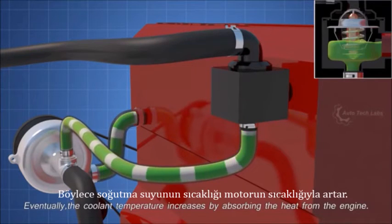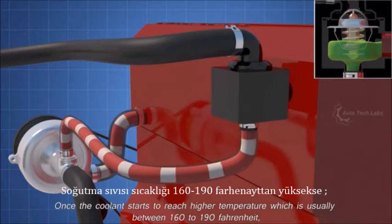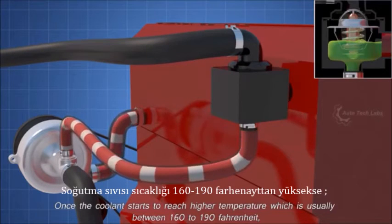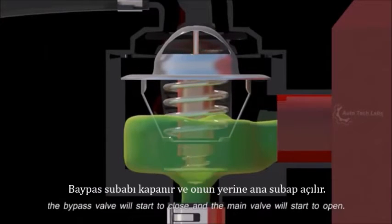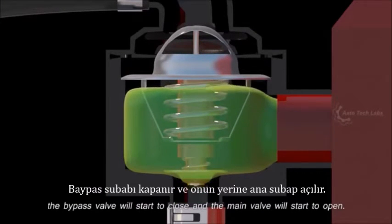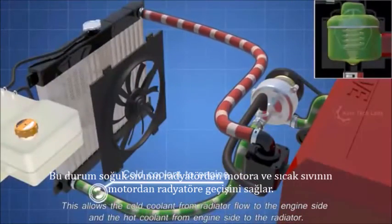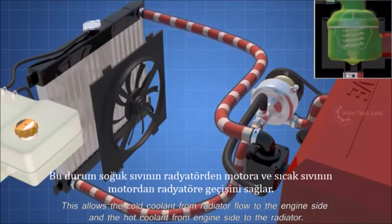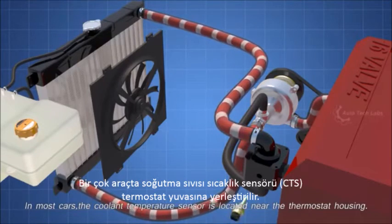Eventually, the coolant temperature increases by absorbing the heat from the engine. Once the coolant reaches a higher temperature, which is usually between 160 to 190 Fahrenheit, the bypass valve will start to close, and the main valve will start to open. This allows the cold coolant from the radiator to flow to the engine side, and the hot coolant from the engine side to flow to the radiator. In most cars, the coolant temperature sensor is located near the thermostat housing.